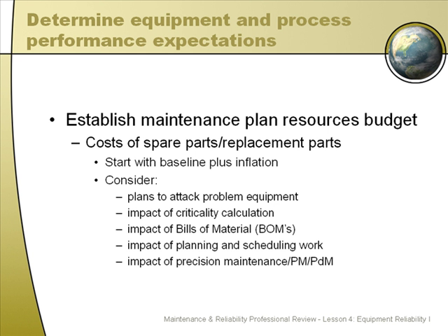Precision maintenance generally allows machines to run longer than they did in the past, and generally speaking, in conjunction with predictive maintenance, precision maintenance will create smaller failures that are easier to correct. For example, you may not need as many bearings and seals and gears and metal mechanical parts as you had in the past because the failures are going to be more subtle. Anyhow, expect that there will be some changes as you become more precise in your maintenance.